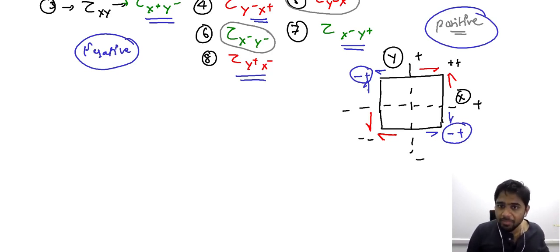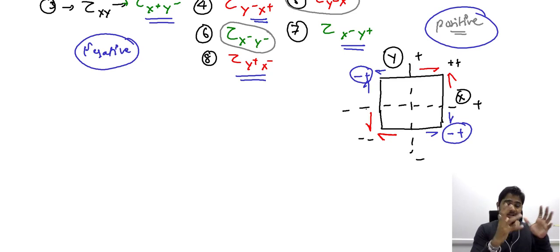When they belong to a combination of positive and negative quadrants, we treat that as the negative shear stresses. So in addition to the equality relation between the different shear stresses, the stress square here also helps us understand the convention associated with the shear components of the stresses.